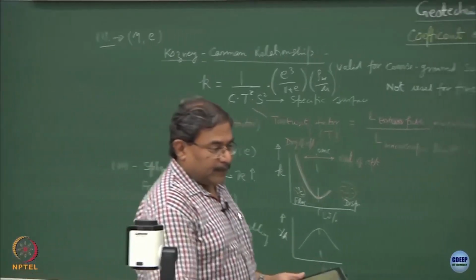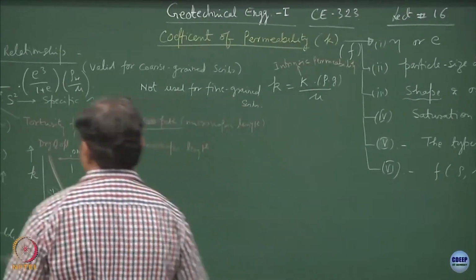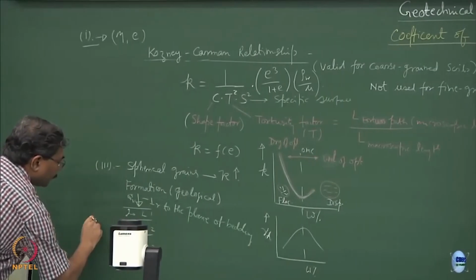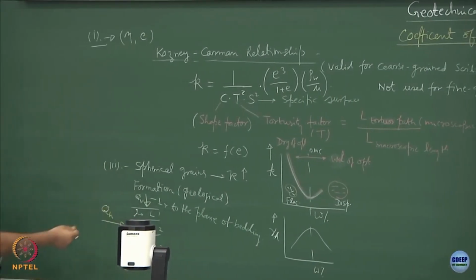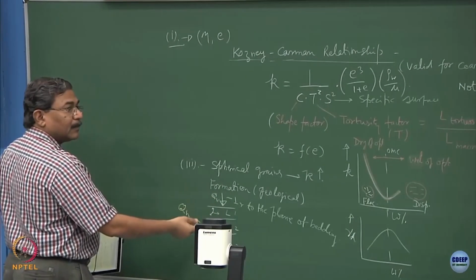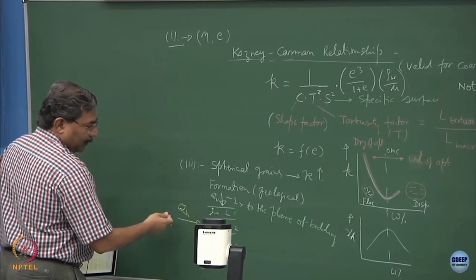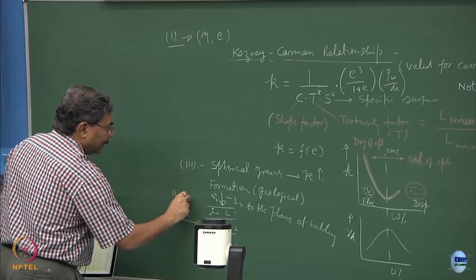I will be more interested in also finding out what would be the QH. So, this is the horizontal flow of the fluid which is taking place through a layered system, alright. Now, I hope you can realize that this is going to be parallel to the bedding.